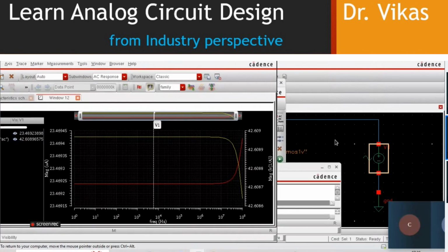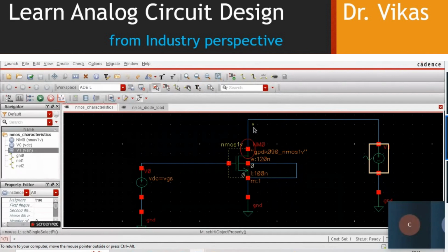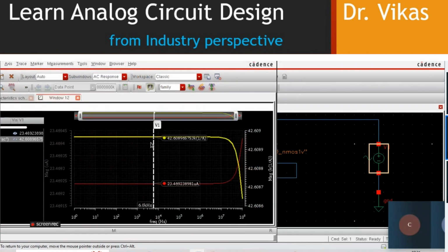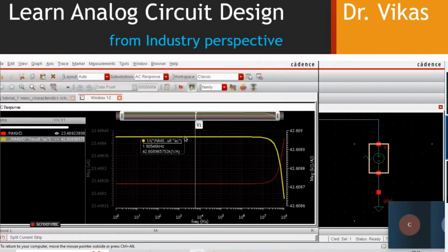And that is the reason why I apply the AC supply. In that AC supply, you mention the magnitude, because that is basically the voltage, how exactly we push some voltage over here. Through this voltage, whatever current is generated over here, that current will fetch me the output resistance, and that's what we have seen. So this is basically the R out, including all your R naught and RL, if anything is there. If nothing is there, then that would be your final output.